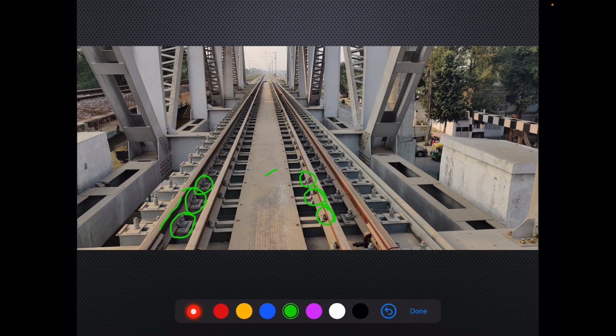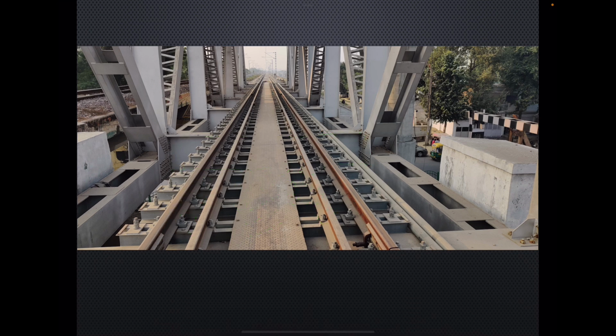And inspection pathway, this is inspection pathway. It is simply bolted at 2 points on each sleeper like this. Okay. So this channel sleeper is basically resting upon the stringer top flange, and the stringers are in turn resting on these cross girders. So this is the basic arrangement.